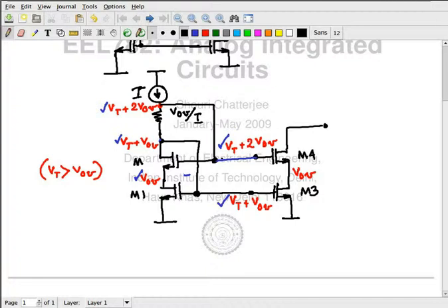So what have I achieved here? First of all, I have achieved the precise mirroring, which you have seen. I have explained already. Number two, I have achieved a huge amount of power savings. Instead of the 3 current sources, I have boiled it down to 1. What's the bad news? The resistor is the bad news. Okay. We don't particularly enjoy using resistors. You get something with this. Right?